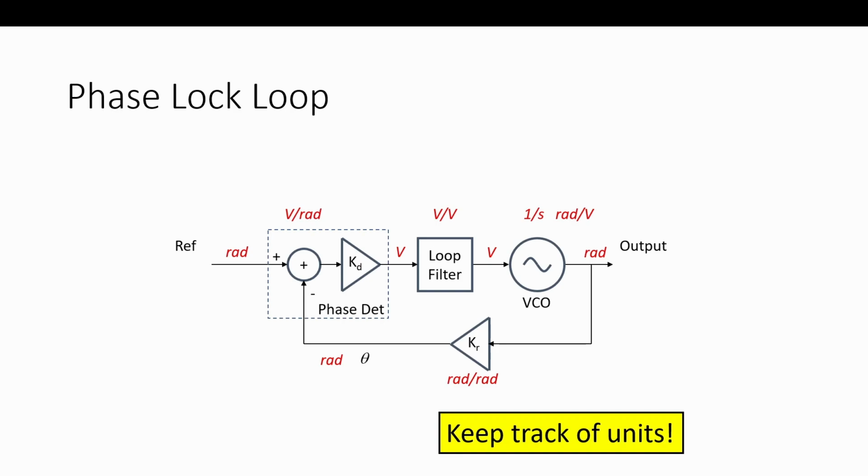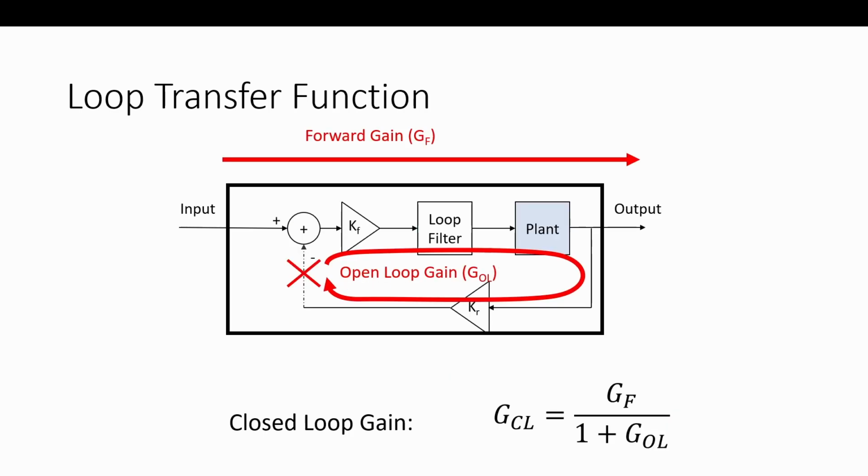In implementation, we're still providing two real sine waves or whatever we're doing. We're getting a phase difference at the output, but in the model, we're just going directly to the units of interest. Right? And then we'll have our loop filter. In this case, a loop filter, its units at the input is volts, its units at the output is volts. So that's important. Each of these blocks, the units have to match, and then we'll be successful in terms of doing that.